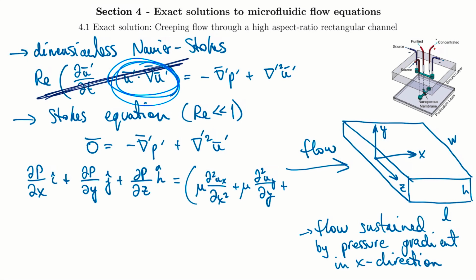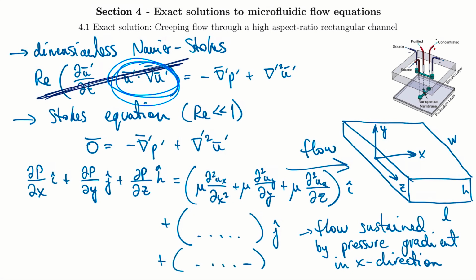So write this out. Okay, so that's the X component of our viscous terms there. And this, of course, I'm writing dimensionally. Again, I had it non-dimensionally above, but I'm writing it dimensionally here. We know what the J and the K, so the Y and the Z terms would be, so I'll just put that out here. No need to write the whole thing out. We get the idea from looking at the X equation. I'll include that there for completeness.